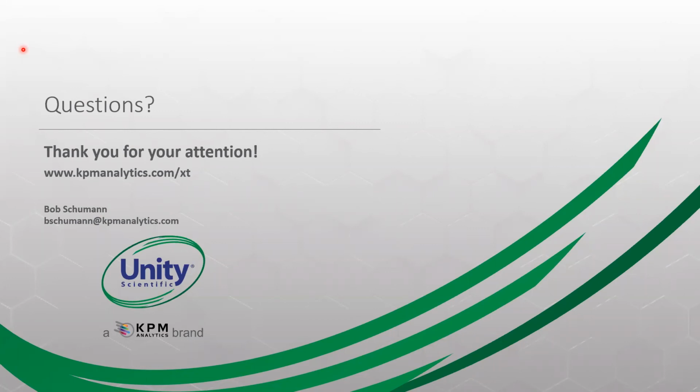Next question, how can you determine if a global calibration for a product group will fit the product we are using? In our case, it is finished aquafeed. Okay, good question. One of the best indicators of this are the outliers. One of the things that happened in the last 15, 20 years is that we developed various statistical methods for determining whether or not the sample that you're analyzing is represented or fits in the calibration. And we do this through various spectral outlier types.